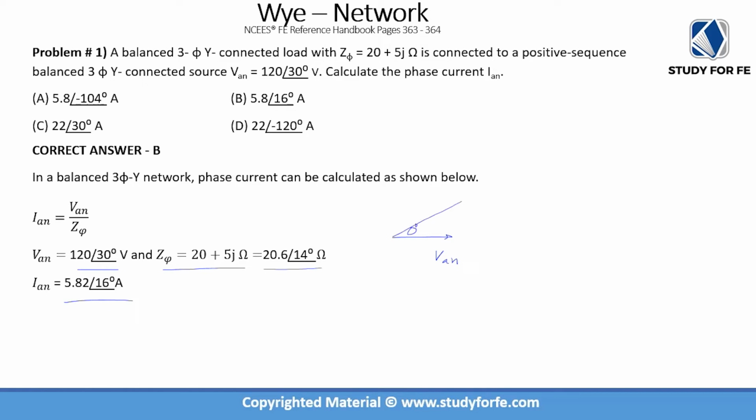They believe that the 30 degrees only applies to the phase voltages, but this can shift as well. If your phase angle becomes 30 degrees, because it will rotate, you still have an additional 30-degree phase shift between your line voltages and your phase voltages.